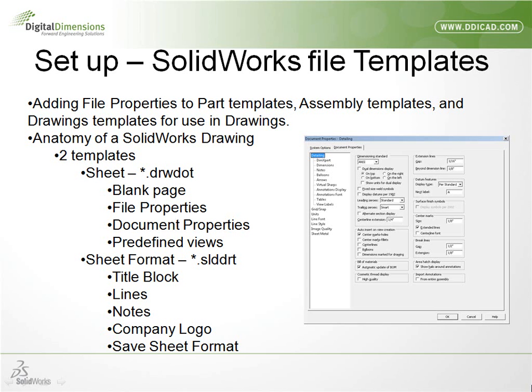As we continue on with the presentation, and I leave SOLIDWORKS file templates, best practice states to have a protected backup of your master templates. It takes a while to figure out which file properties populate the title block, which assembly properties are going to populate the title block, and finally which drawing file properties are going to populate the title block. So after you figure that all out, you want to protect your time by putting a copy of these templates either in your PDMWorks vault on the server or burning it to a CD or a DVD, some read-only format that nobody will mess with.